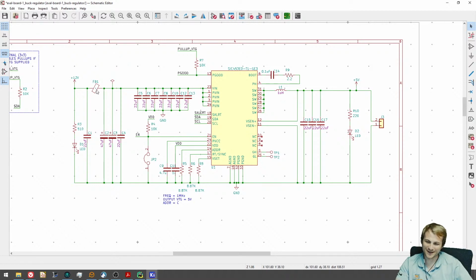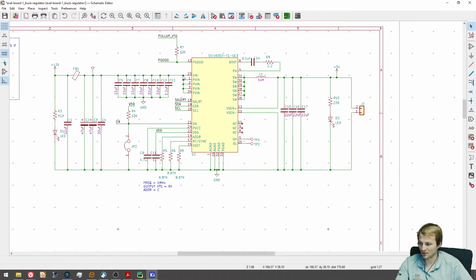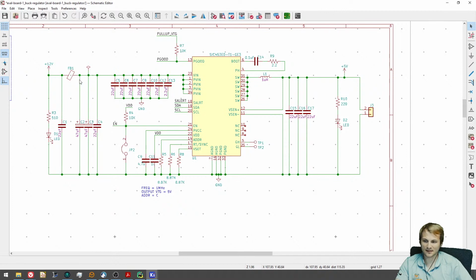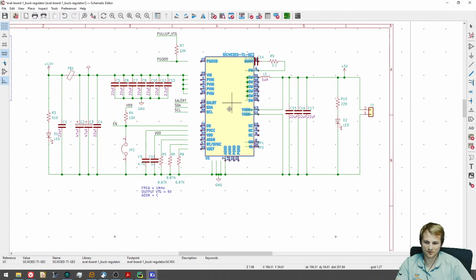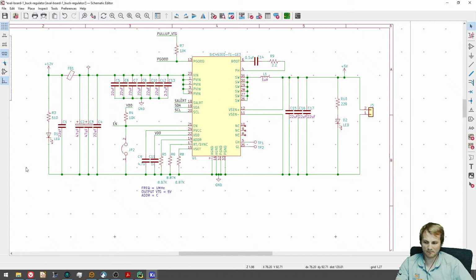You can get away with it, but for a high-speed microcontroller, it's about the single worst thing you can do. It seems like a good idea because the theory is, oh, any of your digital switching noise can't get back onto your main power supply, but that also means any of the high speed switching can't grab power from it either. It essentially blocks it off.